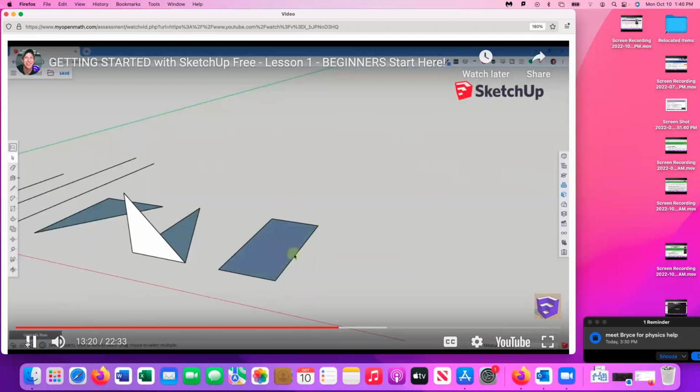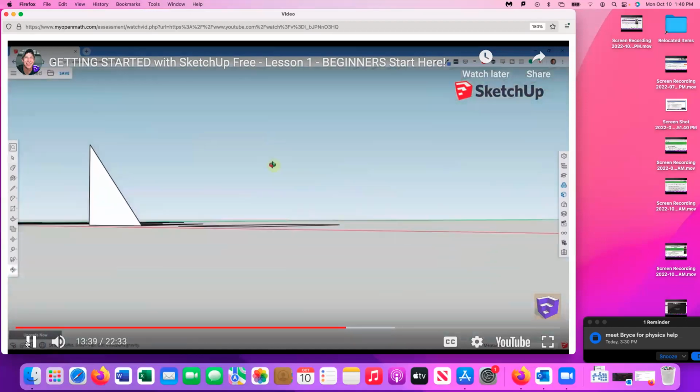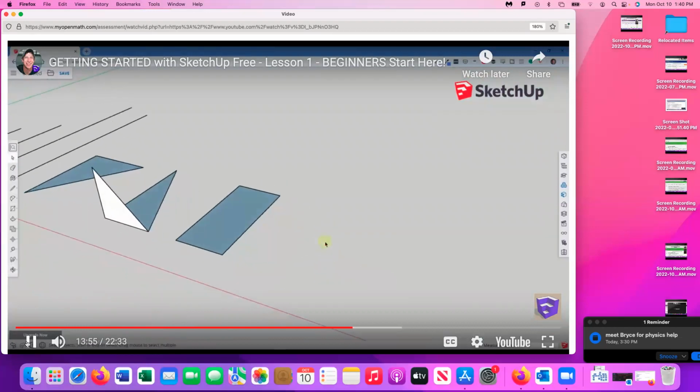And so another thing to note is sometimes a face like this one, you can actually select it, and you can see how this is indicating that it's selected because you get all of these little dots in here. Usually things turn kind of a bluish color when they're selected inside of SketchUp. Well, let's say this face got selected, then you hit the delete key to delete that face out. Well, if you wanted to heal that face back in, what you could do is just trace over one of these edges with the line tool, and you can see how this fills this back in whenever we draw that edge.